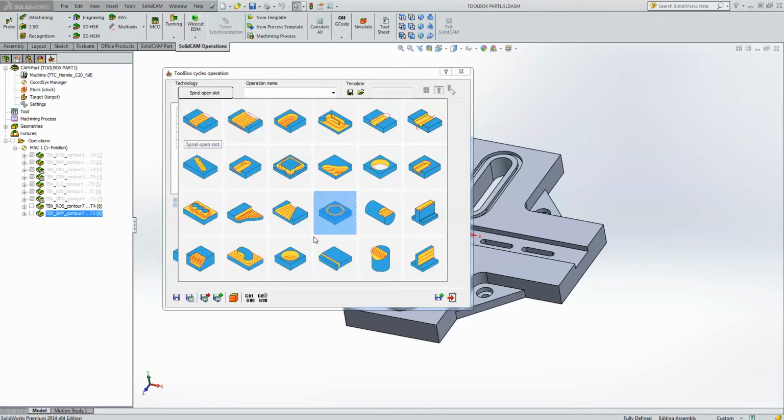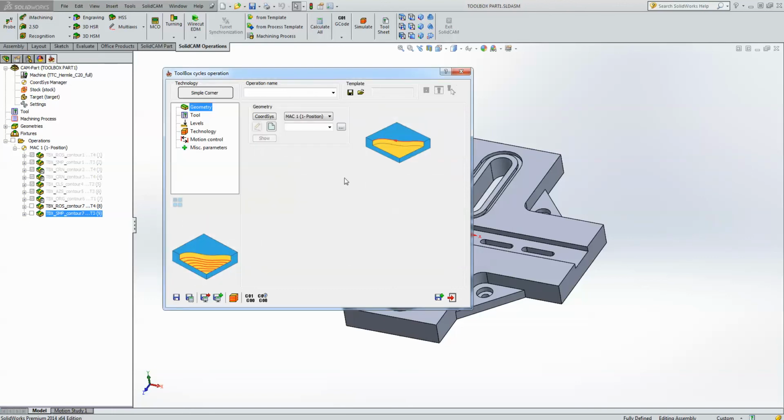We'll use the option, as I said, Simple Corners. Okay, now in the Simple Corner, as you can see, I have to pick just the inside corner itself, just the inside geometry itself as my chain. This and this corner, the actual corner itself, is automatically closed by itself. Now what's important though is the direction of my chain, because it closes off whatever's to the left side of the chain itself. So the direction in this particular case is important. That's why we have an arrow showing it on the actual diagram over here.